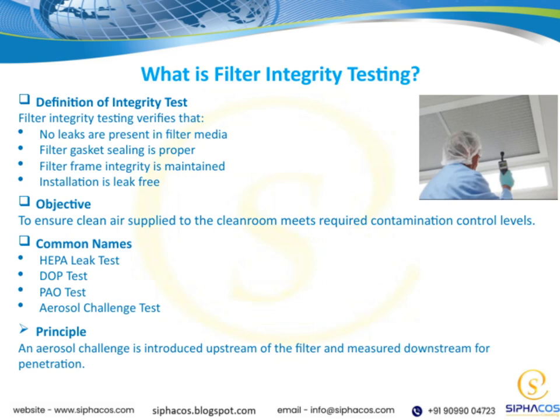It also verifies that the gasket sealing the filter is properly installed and sealed, ensuring no air escapes around the edges. Additionally, we want to confirm that the filter's frame remains solid and intact, because any damage there could lead to failure. And finally, it's important to check that the entire installation is leak-free, so the air passing through is truly clean and free of contaminants. The main objective here is to make sure that the clean air delivered to the cleanroom truly meets our contamination control requirements. This is vital for maintaining product quality and worker safety.